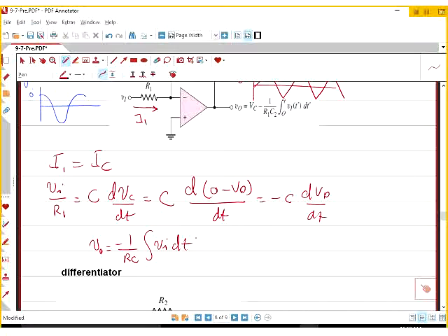For your design, all you need is to design R and C based on the omega, and omega comes from your frequency, to make the whole thing to be 1. So the gain has to be 0 dB or just 1. So when the input is 1 volt, I'm expecting to see the output exactly 1 volt, but with a 90-degree phase shift. Question?